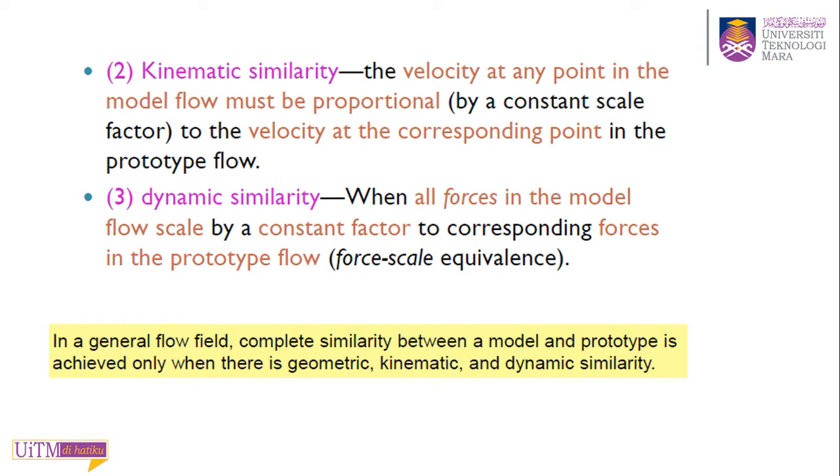And the last one is the dynamic similarity, which is about the forces in the model. If you have the model, the car or the boat or whatever, all the forces in that model, such as viscous forces or drag, whatever, the values of those forces must also be proportional to your prototype by a constant scale factor. So geometry, kinematic, dynamic. There are three conditions that you must ensure to have similarity between your model and your prototype, or the real one.